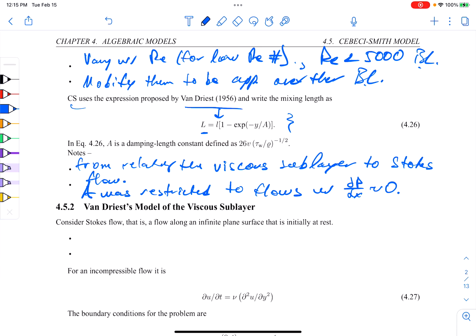Well, it's definitely a very, very slow flow. So when you take the Navier-Stokes equations and your flow is going very slow, it's dominated by viscosity. And that means the nonlinear term in the momentum equation drops away. The u partial x term, for example, would drop away because it's so small. It's a very small term, and the nonlinear effects are negligible.